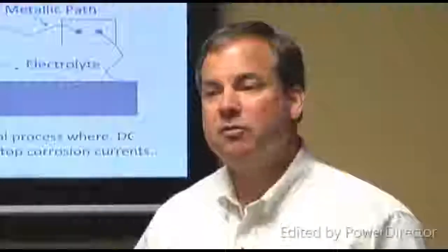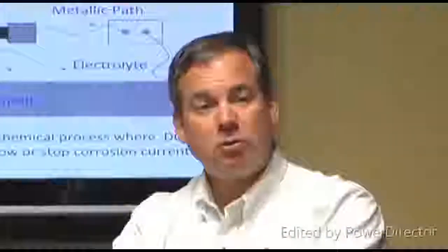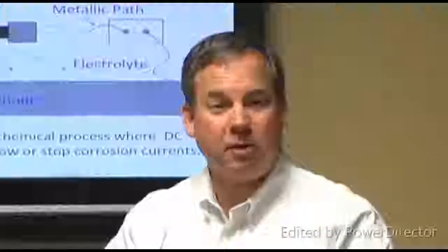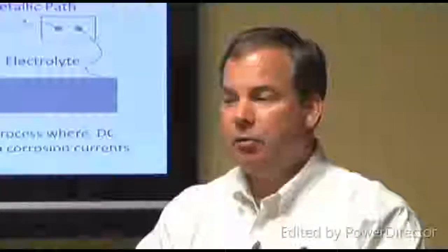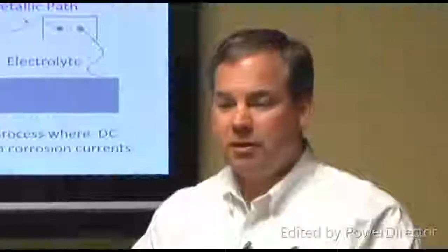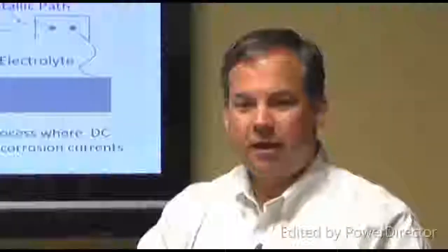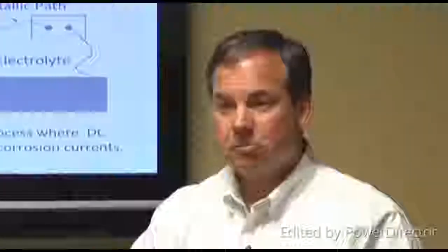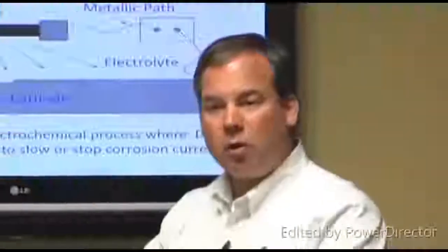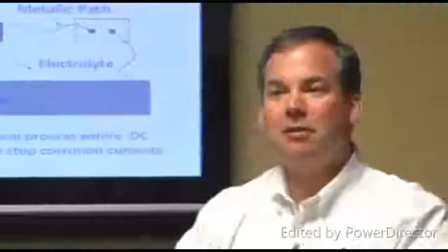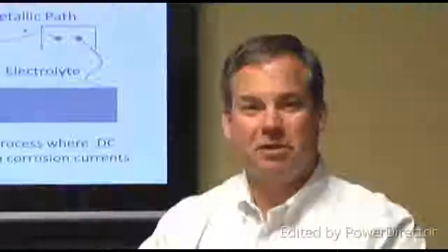So if somebody were to come to us and say, I've got this above ground storage tank and I'm worried about the corrosion of my tank bottom that's in contact with soil and the tank leaking, a very common application for cathodic protection, and you find out that tank's 22 years old and a survey of the floor found 80 to 90% corrosion, putting CP on it probably won't keep it from leaking. In fact, it might actually encourage leaking, because as you flow current onto it, rust particles will start to be pushed away a little bit, and now all you've got left is maybe a real thin piece of metal.